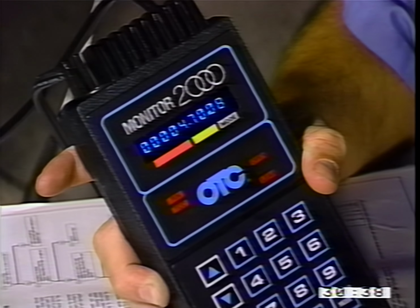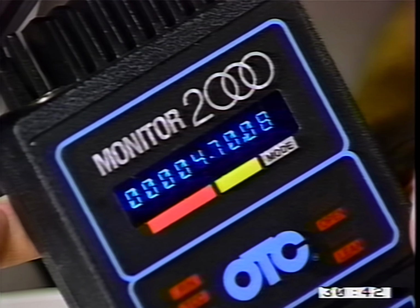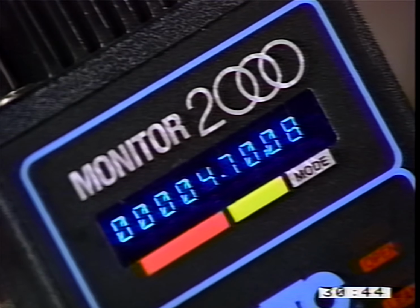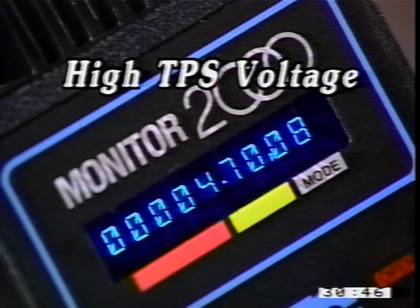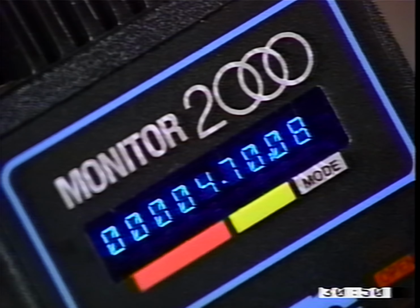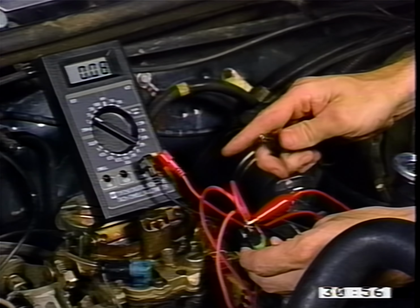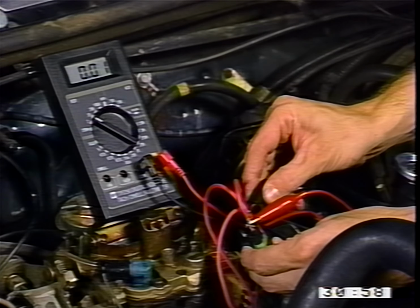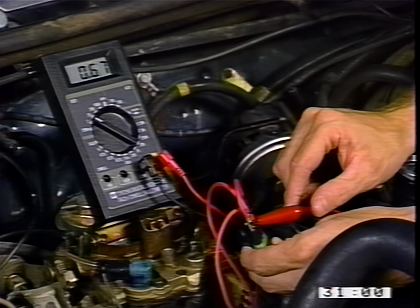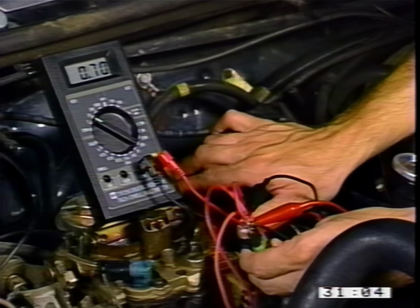Generally, we see about half a volt on most GM applications. A code 21 will set if there is more than 4.5 TPS volts, either with the ignition on or the engine running, or if there is a high TPS voltage, or if there is a low airflow. A condition must have existed for a time period of from 3 to 10 seconds to set the code. If the TPS does not display in excess of 2.5 volts, the code 21 is considered intermittent. This may be caused either by terminal damage or a dead spot in the TPS.